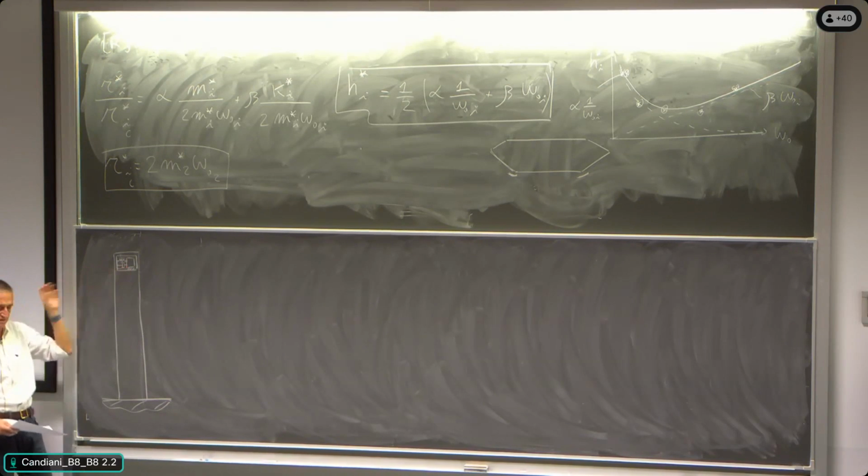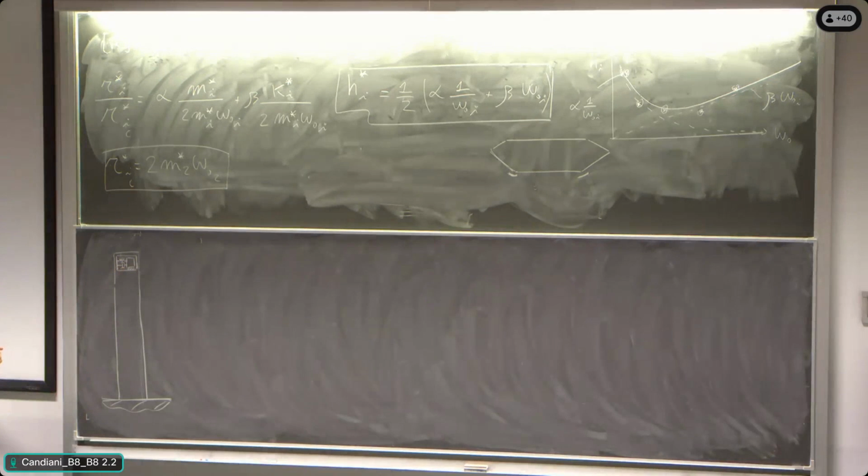So the mass is vibrating a lot. So the amplitude of the mass with respect to the building becomes large. So the damper that is positioned in here is dissipating the energy, and so it is increasing the non-dimensional damping of the mode that has been excited. All right, is it clear? So the tuned mass damper works in this way. There are plenty of examples. You can find all the examples of tuned mass dampers around the world in the very tall buildings.